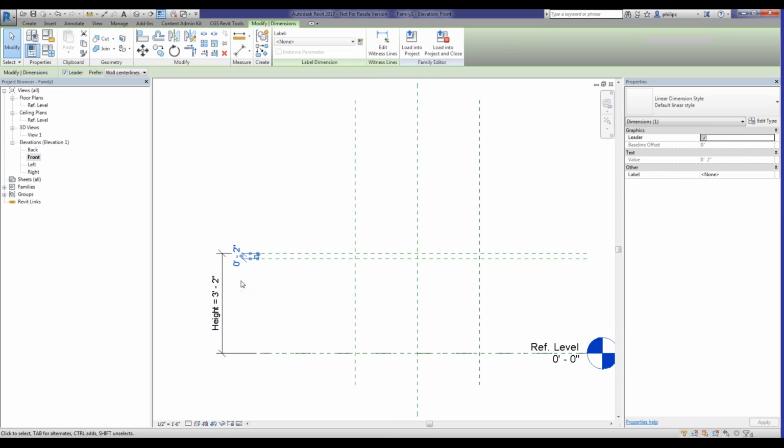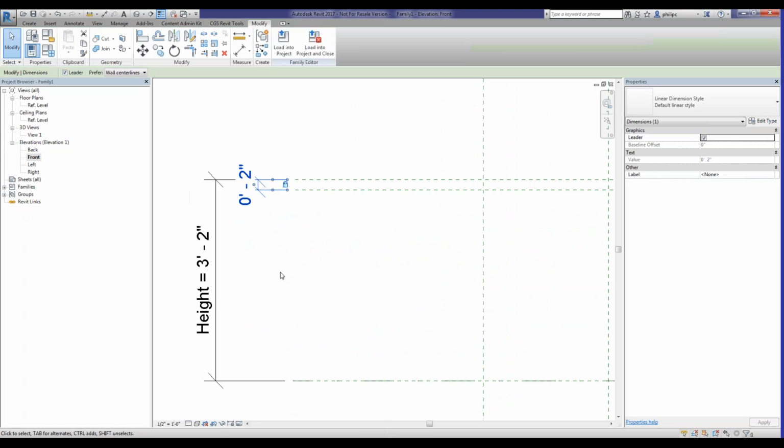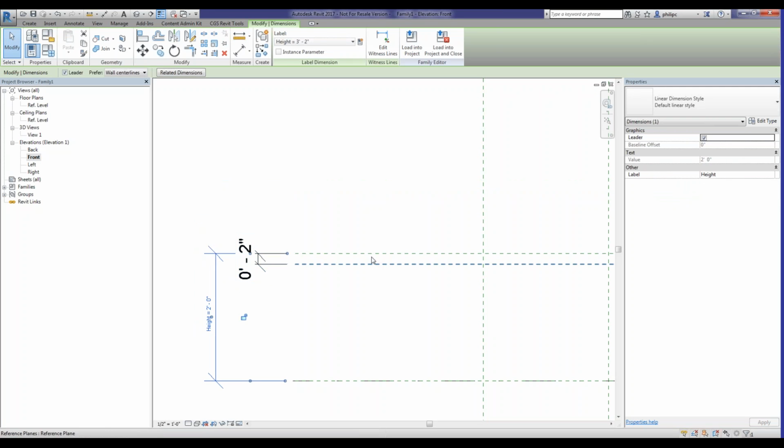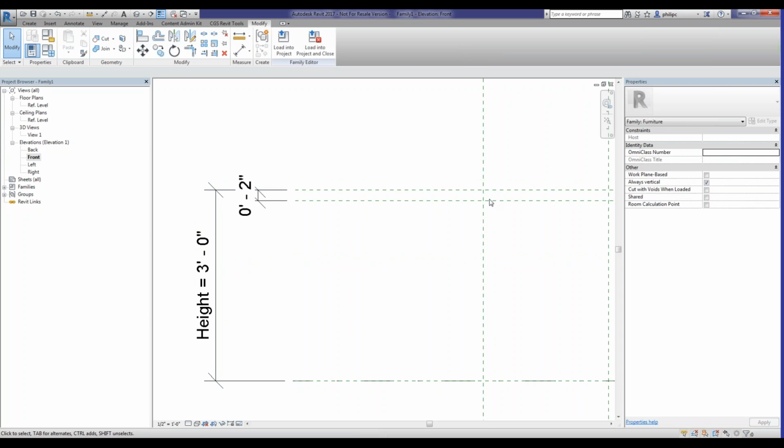So with this one here, the 2-inch dimension, whenever I have just a dimension with no parameter tied to it, I always want to go in and lock that in. So the 2 inches is going to stay consistent. If I adjust my height to a different height here, you'll see that both of those lines change with the change of the dimension that I've got there. So if I add a tabletop to this, that tabletop will adjust up or down from where I create it.